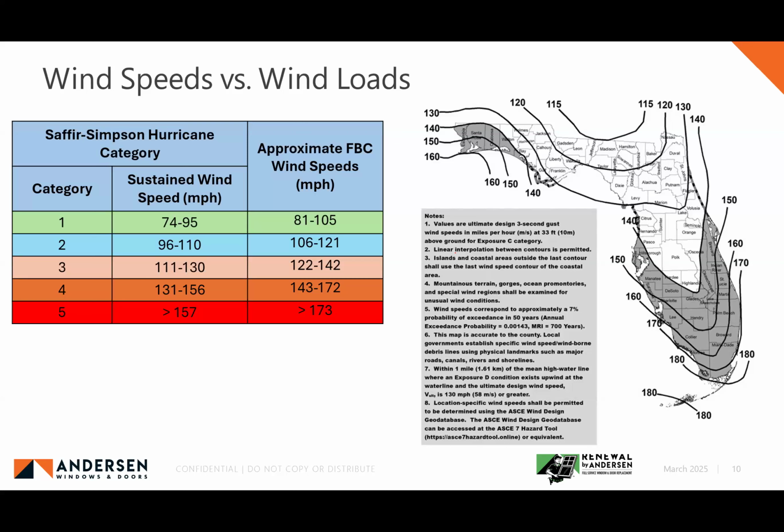They're average wind speeds over a 1 minute period, and they collect this data with dropsondes and other technology, I think primarily through dropsondes. They drop these devices from the planes, out of the sky, and they drop down into the hurricane and measure the various parameters that they're looking for. Okay, the wind speeds we use in the code are 3-second gusts.